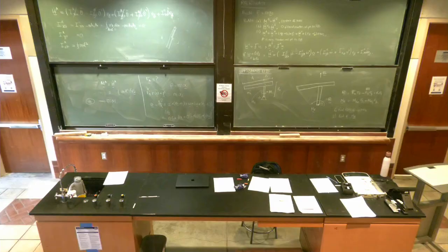Where is your free body diagram? This force here. What do you think about it? If I'm considering the system to be these two combined, then this is internal, right? So I would encourage you to draw the system on its own without the support, and then that's the free body diagram. Oh, and you also need to add the applied moment to the free body diagram. Don't forget. I just wanted to use the vector equations so that you don't make mistakes, okay? Yeah, so just be careful. You're doing great, but just be careful with that.